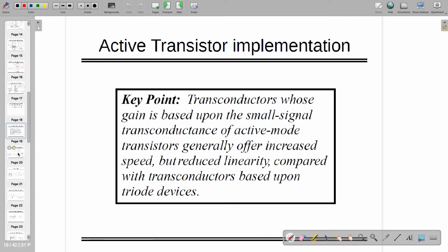Okay, so it's all about fine. Sometimes you are implementing an active transistor. When we are saying active, it's actually for the BJT. As this book is talking about BJT as well as MOSFET together, that's why this word is coming into the picture. Remember, active in BJT is equal to saturation in MOSFET. However, there is one more term: saturation in BJT is equal to triode in MOSFET.